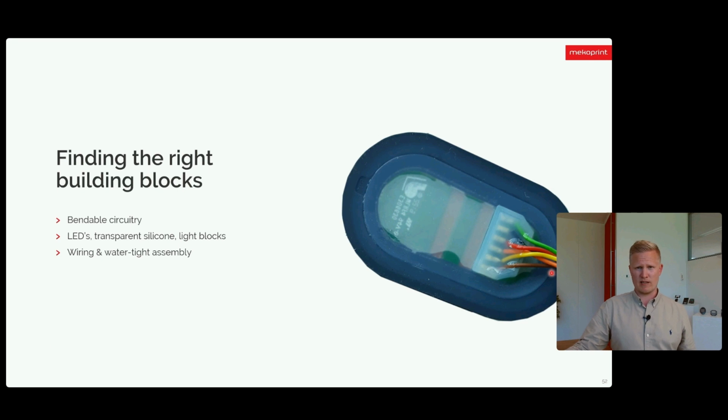It also had to be watertight, and we achieved that by gluing the two silicone parts together, a silicone part with the PCB and an extra silicone here to seal it around the edge. And you can see here, the cable connection that is soldered onto the PCB is also sealed by using a potting.